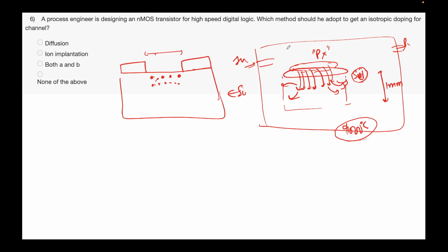And what if we keep the temperature elevated, let's say 1000 degrees Celsius, what will happen? The phosphorus atoms will say, oh, the concentration is very low here, so they will start migrating, diffusing rather, in this direction. What profile are you seeing? Let me draw it in a different color. The profile you're seeing of phosphorus is something like this.